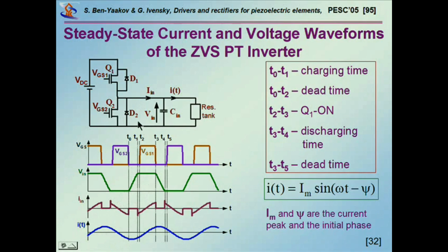Now, the problem is, of course, that you do have to have sufficient current so that the equivalent resonant circuit, that is this inductor plus the total capacitances, will be able to change this voltage, and this time is approximately a quarter of a resonant period. So the problem is how much current can you get here when the behavior is inductive.